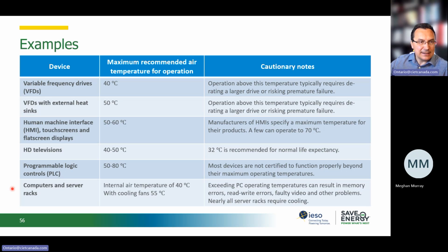For example, servers are designed to operate at higher temperature so that we can improve the efficiency of the data center. We are looking at 40 degrees Celsius, and if we have cooling fans, the server temperature can actually operate at 55 degrees Celsius. So it's quite a significant amount of heat that is generated by these devices.